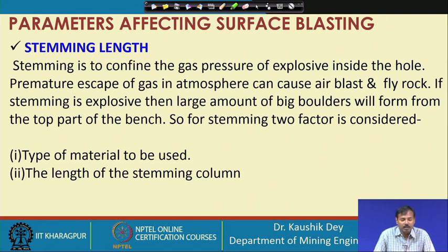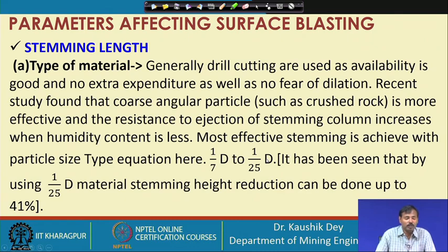If the stemming is large, then big boulders may form in the top part of the bench. When considering stemming, we consider two factors. One is the type of material to be used, another is the length of the stemming column. So, let us look into these two.